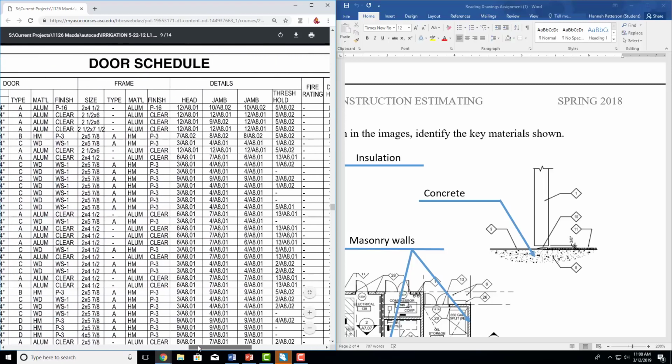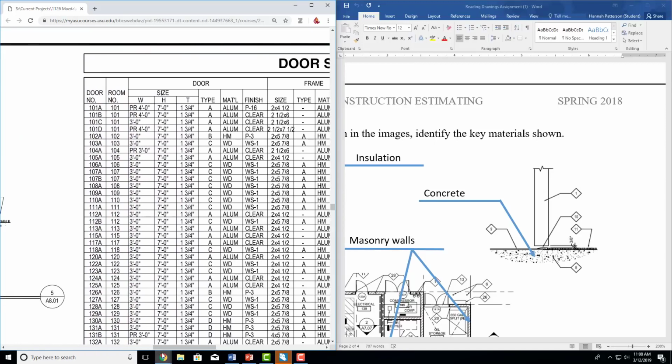A good way to also tell, this is your door schedule. If we knew what room this is, we could actually tell you what that door was made of and everything. Like I was showing you, this room number corresponds to the door number typically. So room 101, 101A, 101B, 101C, 101D. They almost always correspond. Keep that in mind, but not always. So don't assume, just flip to that page and check real quick. But we're going to keep going now with the different kinds of materials.